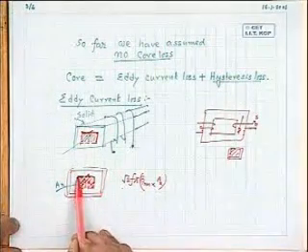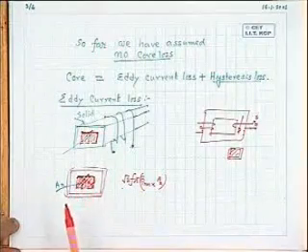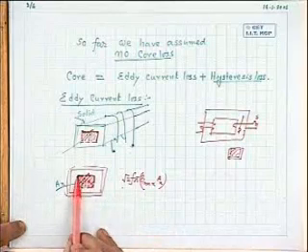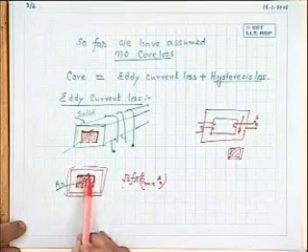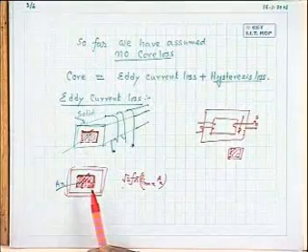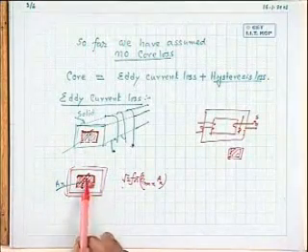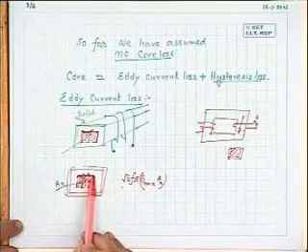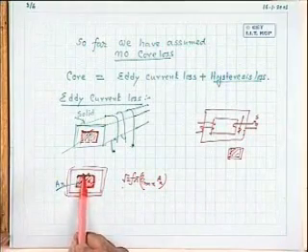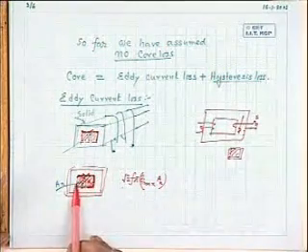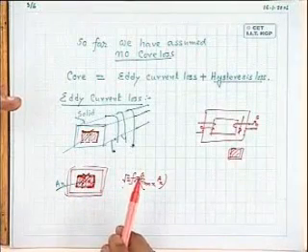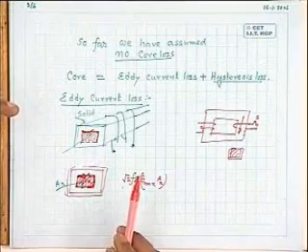As you load the secondary of a transformer, current starts flowing. So there will be some current flowing now in this loop. What will be the magnitude of this current? This voltage divided by the resistance of this path. Let us assume this path is resistive. That much current will flow. And when that current flows in this path, only a single path I have yet considered, there will be I square into the resistance of this path. That amount of loss will take place.